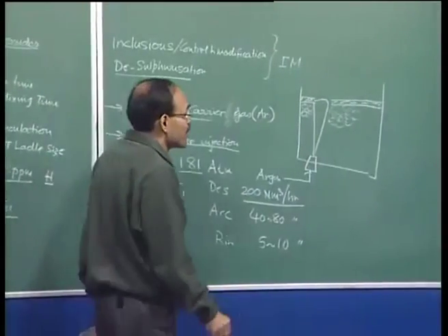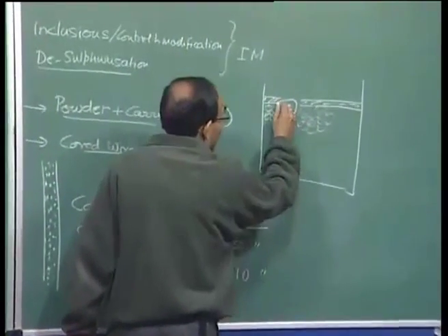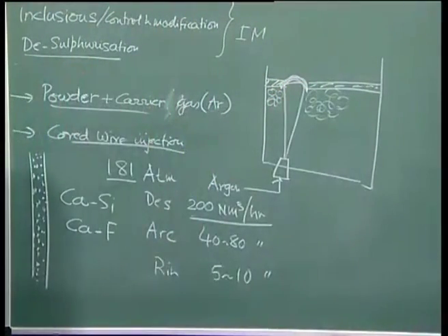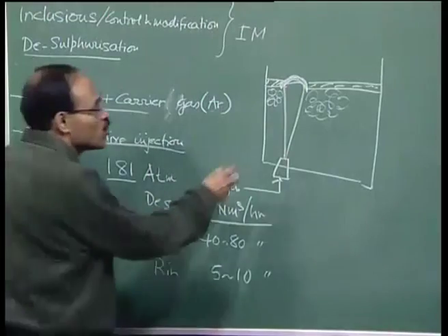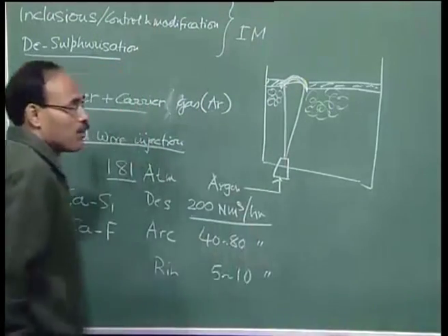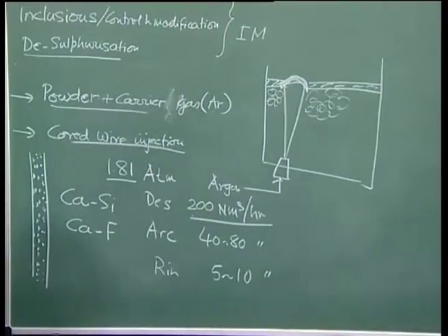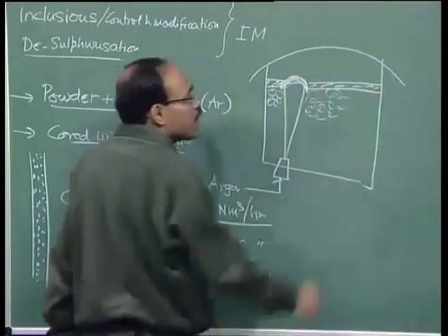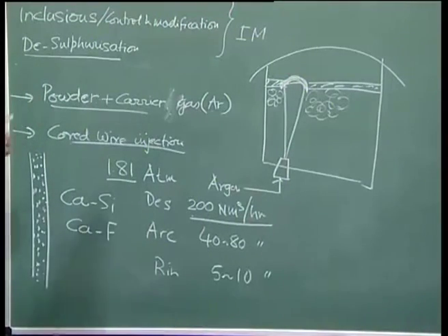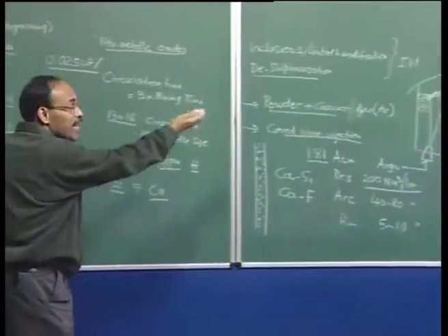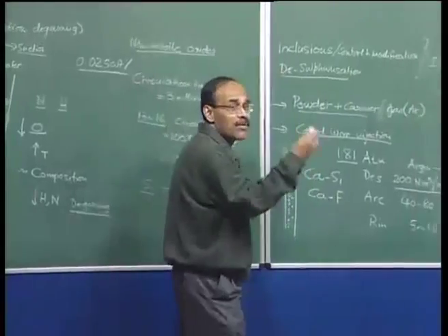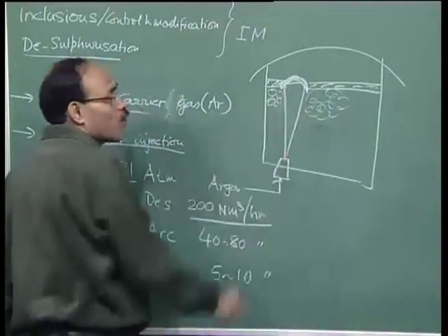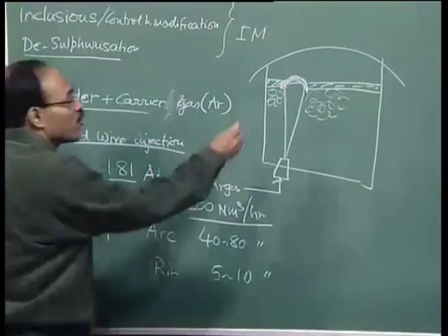And of course, we must understand that when you do this, we have tremendous fluid dynamic activity in the plume region, because the flow rate is very, very large, and as a result we can have a lot of droplet formation, a lot of reoxidation. So it is perhaps desirable that the entire thing is covered up and carried out. Okay, this operation can also be done in tank degassing. For example, desulfurization can be carried out where it is facilitated under vacuum.